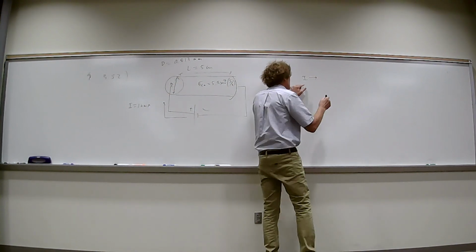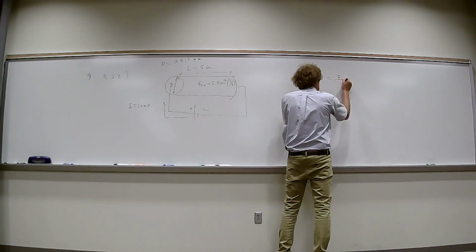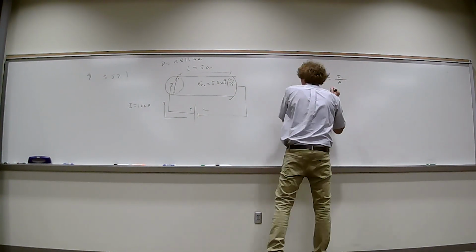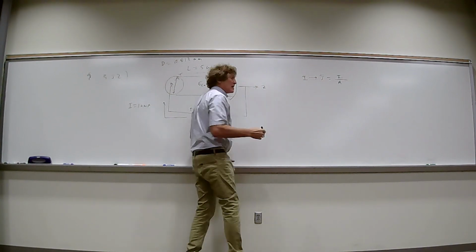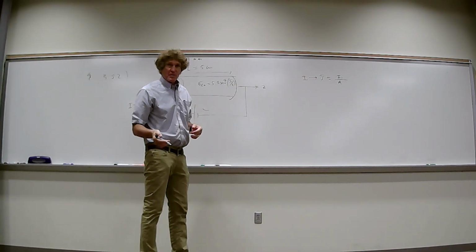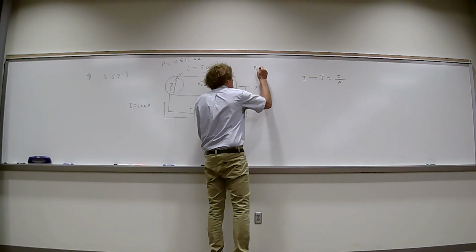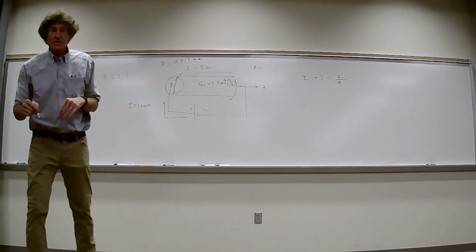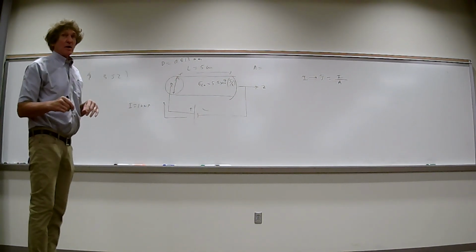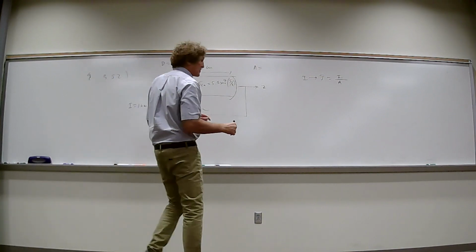The next thing you're going to get is J. And J is simply equal to I over the cross-sectional area in the direction that's flowing. I'm going to just call this the Z direction. Doesn't matter what I call it. Y'all with me, class? So now we need the area. What's the cross-sectional area of a wire of a certain diameter? Well, it would be pi a squared if a was the radius, right? Or pi d over 2 squared if you're going to use diameter.